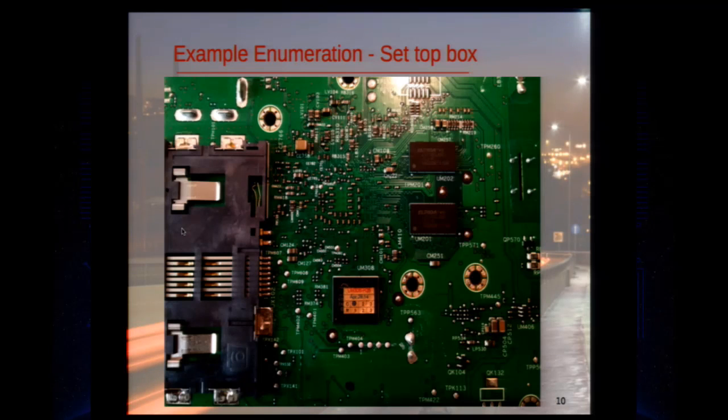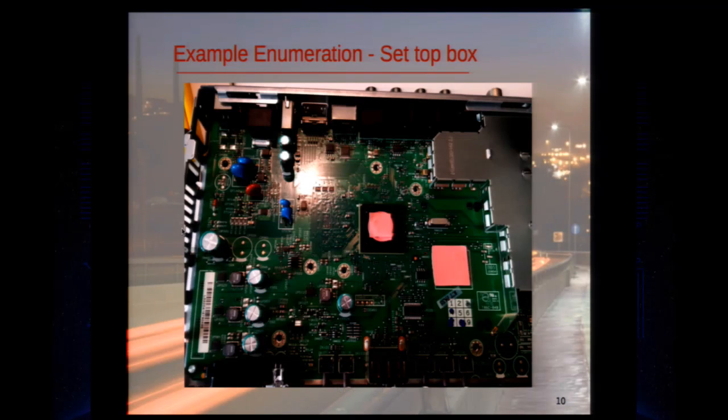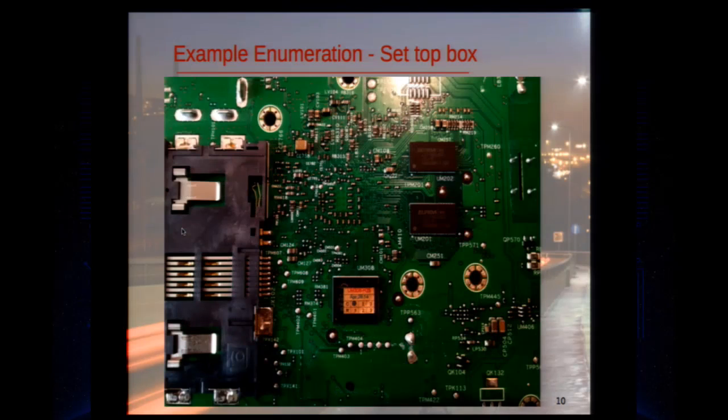Now, we can also look at the underside and learn a bit about where these decoupling capacitors would be located. In practice, what I was told by a lot of people was that these decoupling capacitors are typically directly underneath the device that you're trying to shield, to help avoid any sort of extra jitter, which is effectively what you're trying to introduce to the targeted device. So if you're looking for decoupling capacitors on a BGA package type form, such as this unknown device, usually you could just look directly under it and you'll find the decoupling capacitors right there.